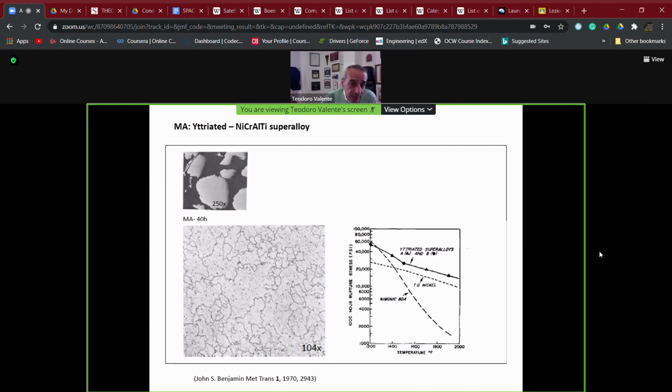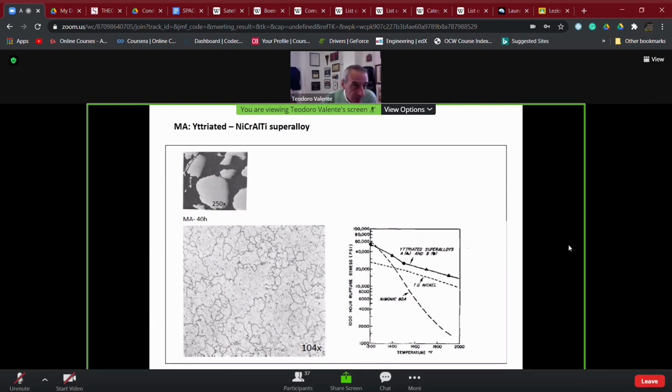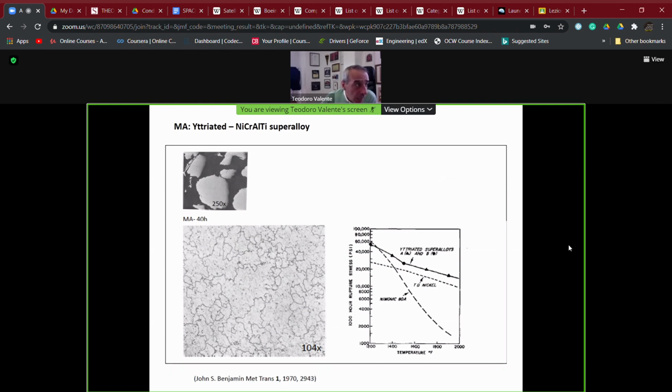Why? Because we expect, but we will have to see something more, that these kinds of materials, due to, as we said last time, the fact that a part of these materials is already an oxide, because we have dispersed oxide inside, can show higher stability at higher working temperature. And this is true, also with some benefits, depending on the working conditions, for creep resistance. Why some benefits for creep resistance?